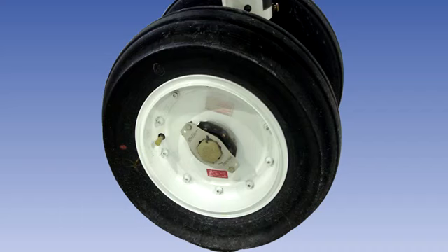Aircraft wheels are either cast or forged, then machined and ground to the required finish. They are made of either aluminium or magnesium alloy. Magnesium alloys are lighter. However, they are subject to corrosion if not correctly treated. And magnesium is flammable, so there is a greater risk of fire. For these reasons, aluminium alloys are normally used, unless low weight is essential.